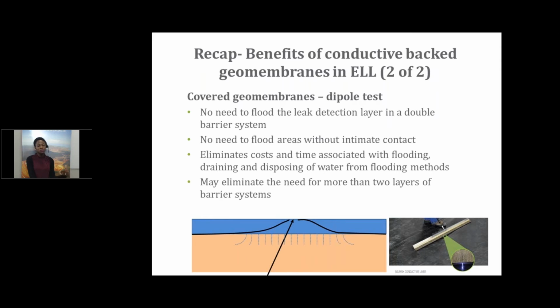And not having to flood and use water-based methods can save some money as well, and the time associated with flooding, say, a leak detection layer and having to drain that layer and having to dispose of the water. I read in a study where they had to flood the leak location layer, and it took about 2 weeks to drain that layer before they could continue operations on the site.